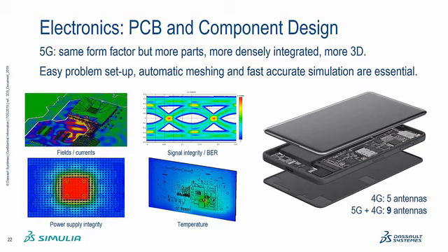Now, an additional challenge that comes in when you're adding more systems is that you're reducing the space inside your device. If you're reducing the space, you might well have more thermal issues, so it might be more difficult to cool the device down. And therefore, looking at not only the electromagnetic performance, but also the thermal performance becomes a very important consideration.